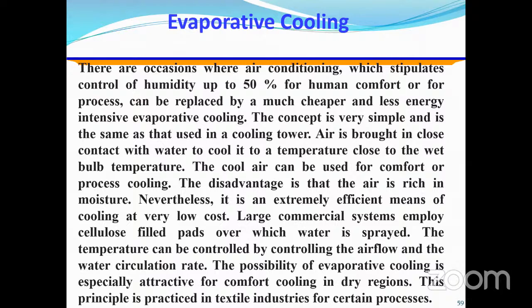Large commercial systems employ cellulose-filled pads over which water is sprayed. The temperature can be controlled by controlling the airflow and the water circulation rate. The possibility of evaporative cooling is especially attractive for comfort cooling in dry regions. This principle is practiced in textile industries for certain processes.